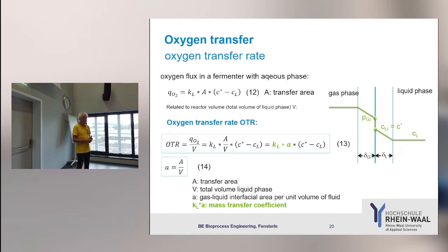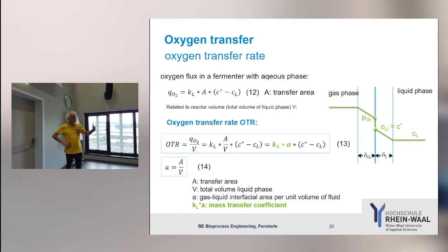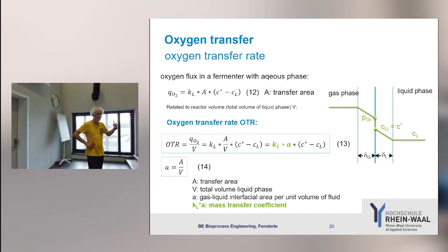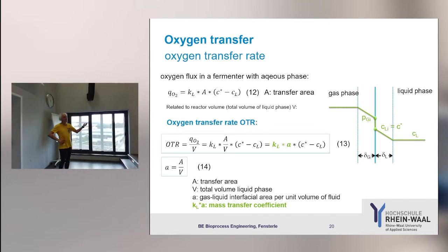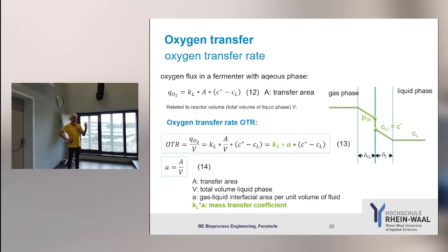And therefore, if you have, of course, an air-lift reactor or so, the only thing determining your bubble size is the sparger. But in an air-lift reactor where you have no stirrer, measuring KLA stuff is even more difficult than in stirred tank reactors, because your distribution of bubble sizes is completely uneven, because you cannot prevent this fusion of the bubbles.